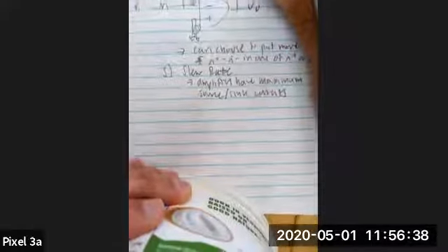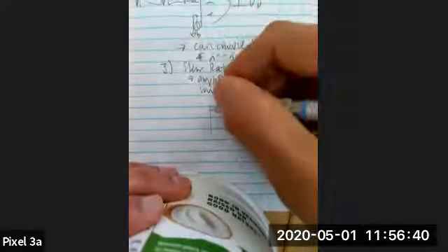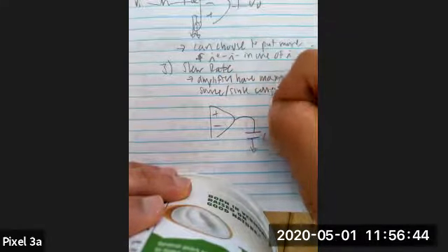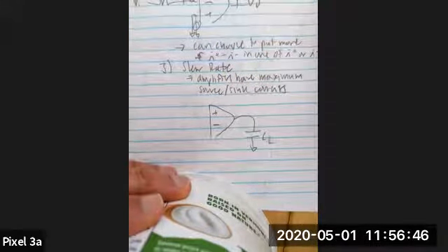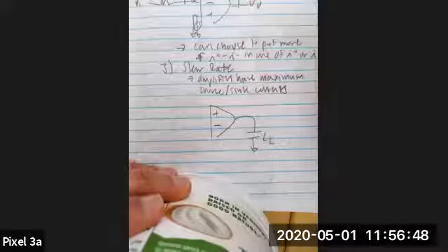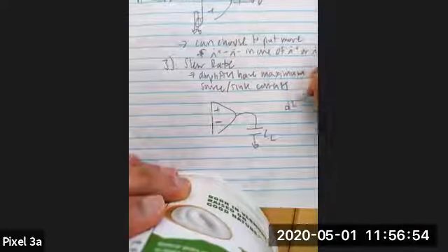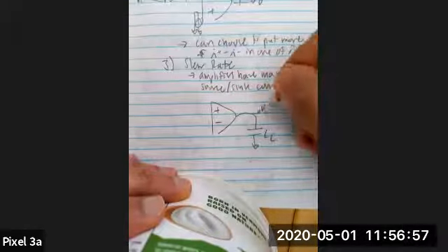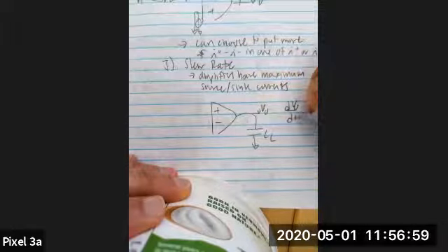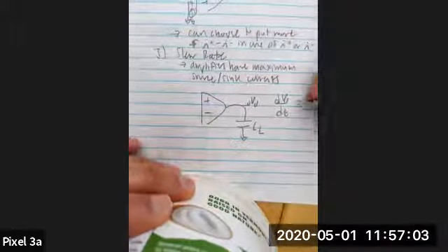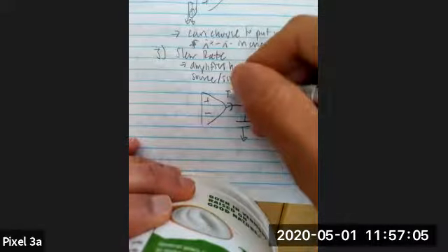How this arises is that we have our amplifier here, and then there's usually some output capacitance here. An expression we can find is that the change in output voltage as a function of time is directly equal to this output current over the load capacitor.